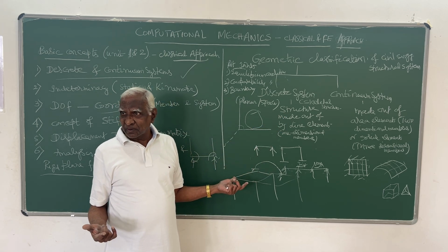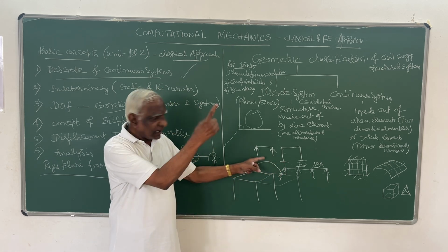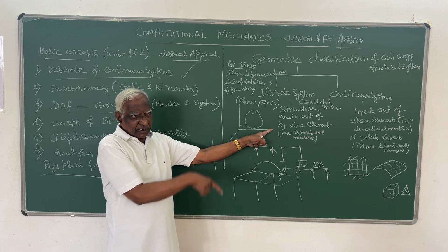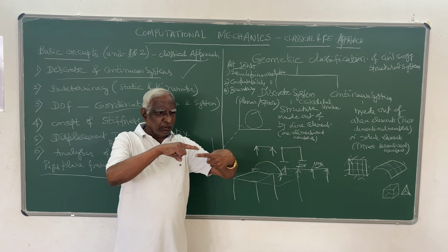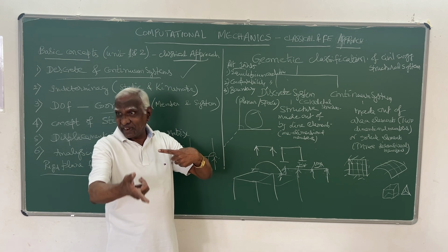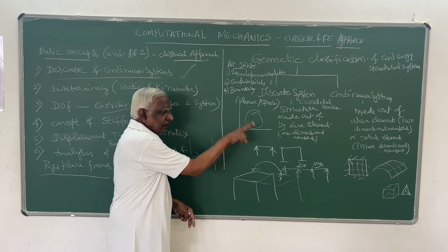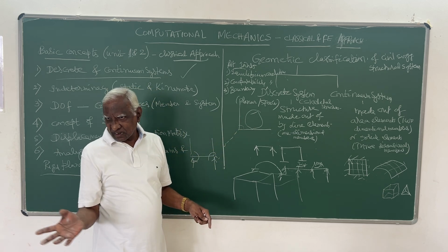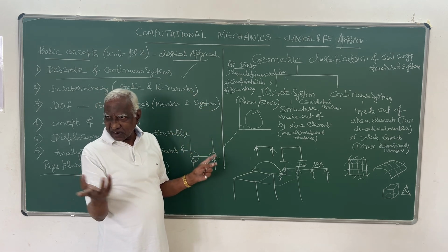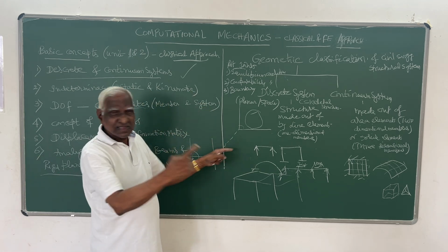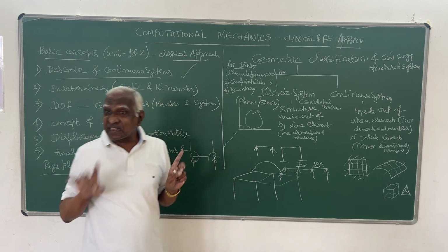Similarly, moment. Moment about x cannot be considered, because moment about x, if you take this as x, moment about x is like this. Correct? This is x, moment about x is like this, it is out of plane. If this is in the vertical plane, moment about x will be out of plane, it is not considered. Similarly, moment about y is out of plane, not considered. Only z-axis moment will be within the plane, so only Mz we consider.